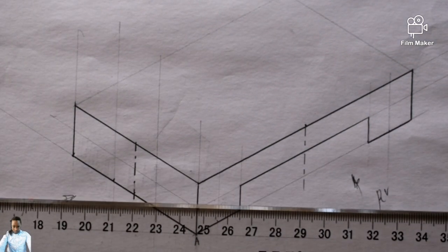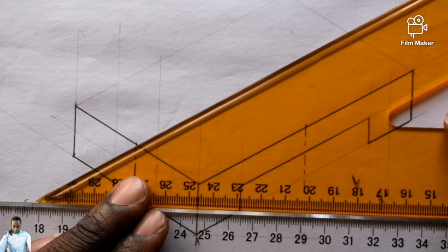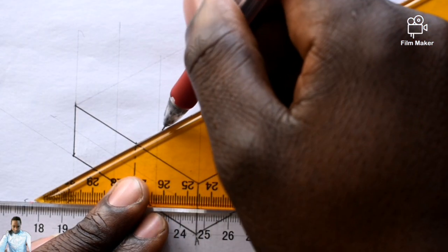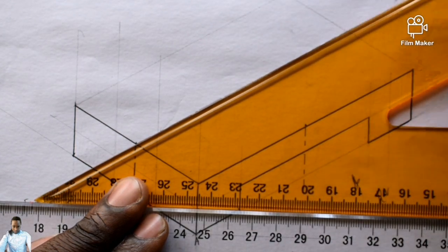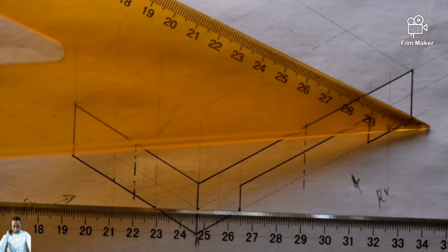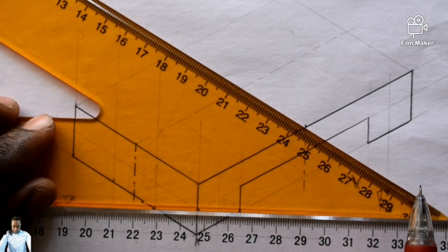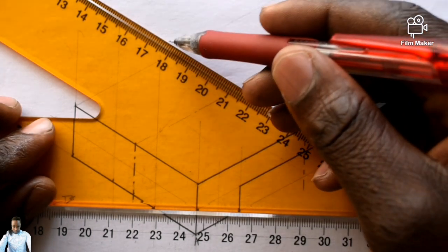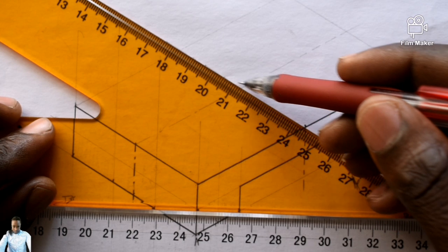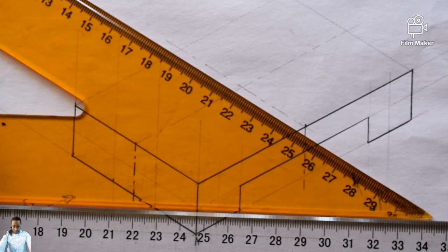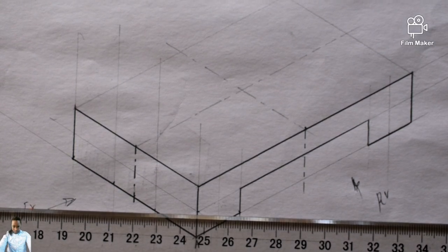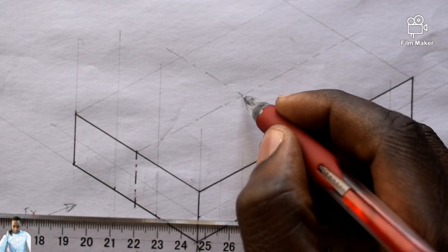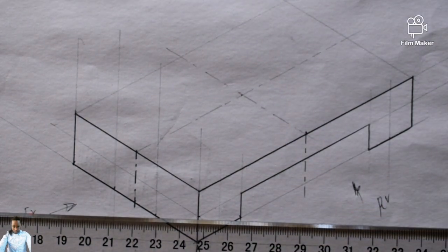So from there, I'm going to take the center. So this one, I'll draw it faint. Draw it faint. Top one. As well as this one, take it at an angle of 30 degrees clockwise, faint as well. Take it faint. So where these two centers are crossing each other, so that's going to be your point, right? This point is very much important. So now let's check. We are having a hexagon.